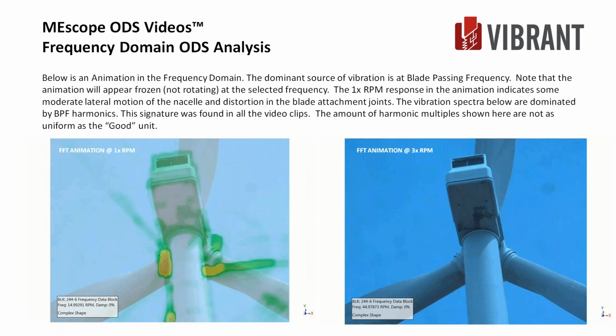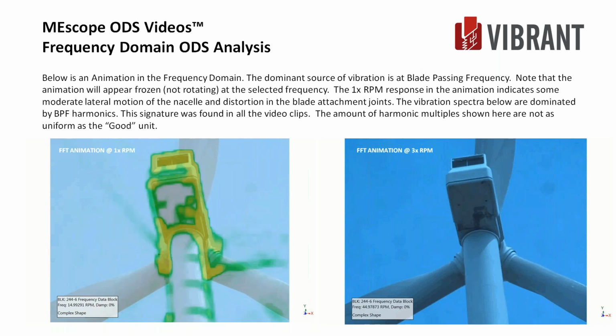If I could do all the units in this wind farm, I could probably pick out the ones that were good and the ones that were bad, and it would be a really nice way to get a good baseline of the field and know which ones are bad behavior units from the start. But anyway, we proved that it wasn't the tower. The balance guy thought that it was a resonance in the tower, and we didn't see that on that unit, which was the worst one, and 5 others that he said we should take a look at.